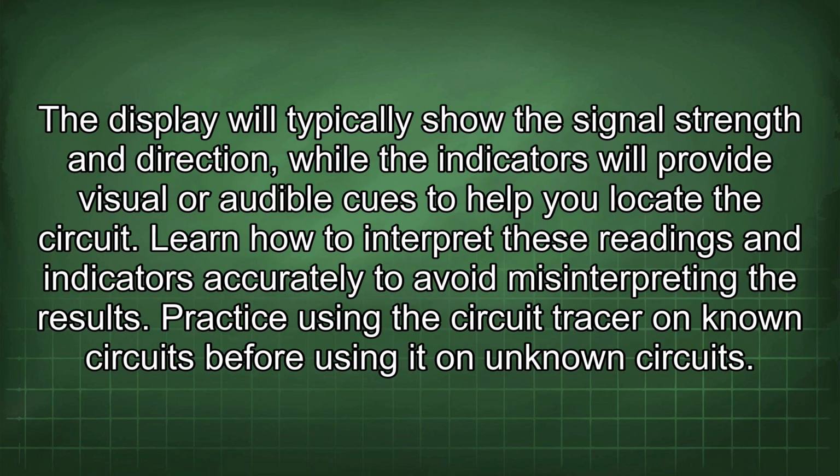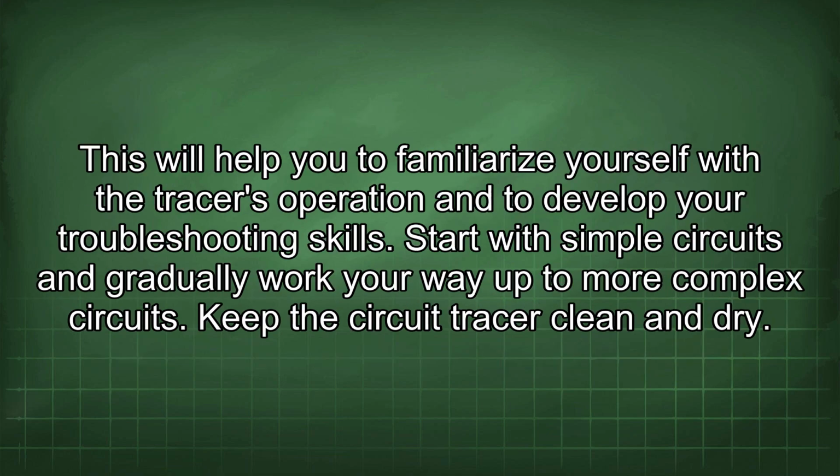The display will typically show the signal strength and direction, while the indicators will provide visual or audible cues to help you locate the circuit. Learn how to interpret these readings and indicators accurately to avoid misinterpreting the results. Practice using the circuit tracer on known circuits before using it on unknown circuits. This will help you to familiarize yourself with the tracer's operation and to develop your troubleshooting skills. Start with simple circuits and gradually work your way up to more complex circuits.